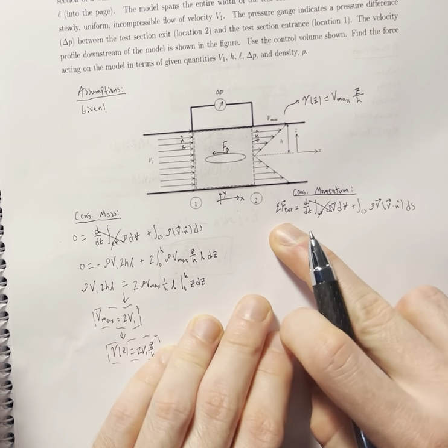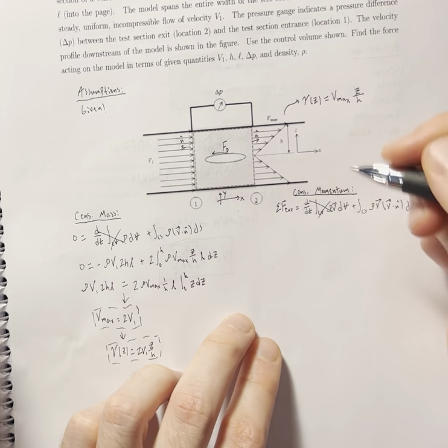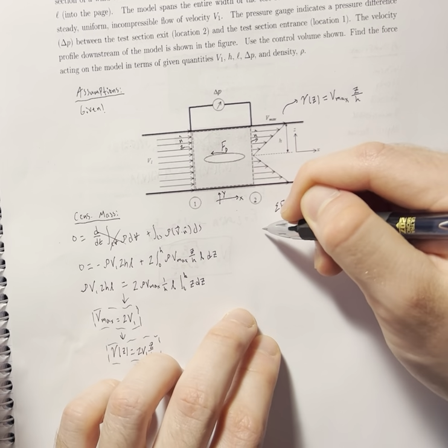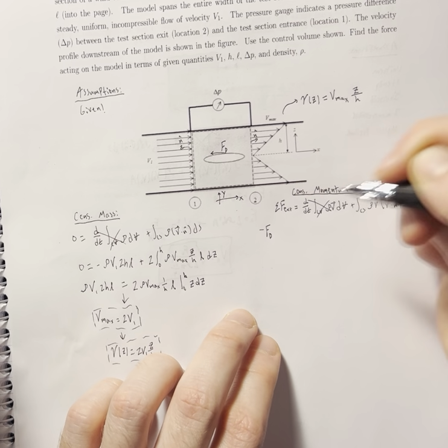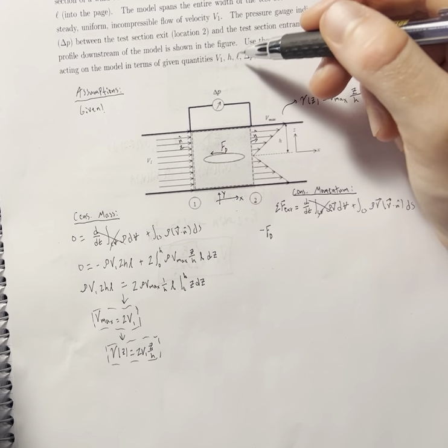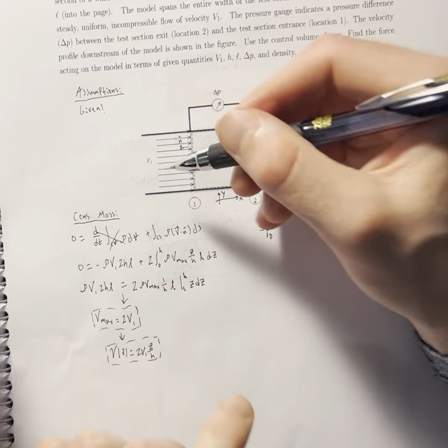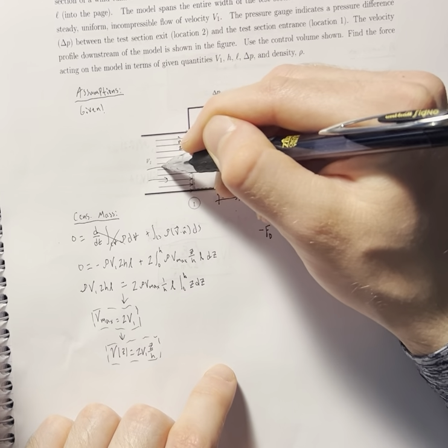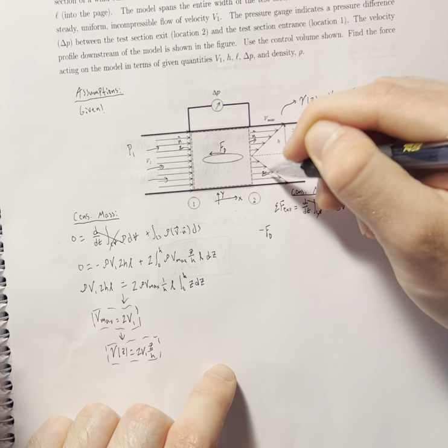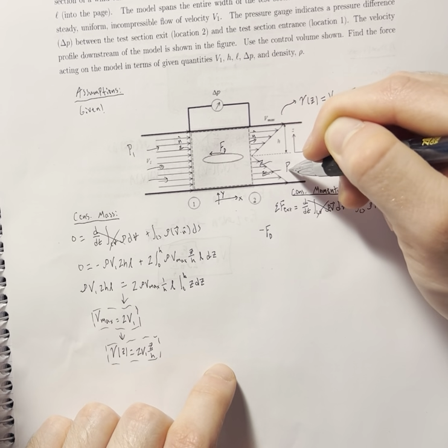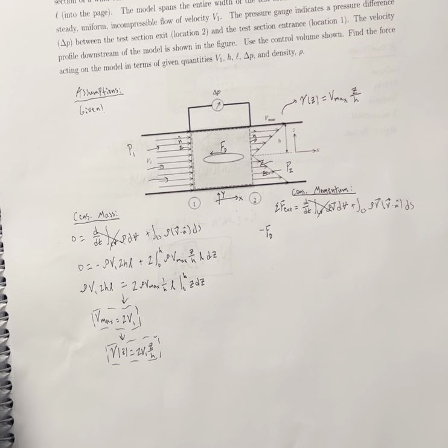And now these external forces, right? First off, we're going to have this negative FD. That's our main one we're going to be solving for. But now we also have these pressure forces we have to worry about. We know there's some delta P here from P1 acting over here and P2 acting from over here, right? Obviously through the whole thing.